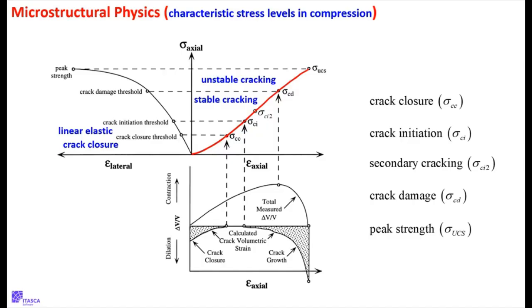So he does this, and then now he has to go and, I don't know, drink a lot of coffee. And what he finds is that if he drinks enough coffee and waits long, he comes back into his lab the next morning and the whole thing is laying there on the floor. It's exploded and failed. Which means that he only loaded it up to here, and yet if you wait long enough, the rock fails. Which indicates clearly that there's a time dependence to the strength. Because the loading went from here to here in about 10 minutes, and this time dependence is a slower process.